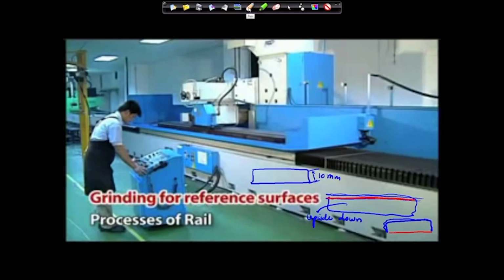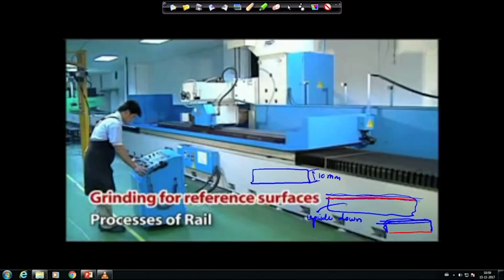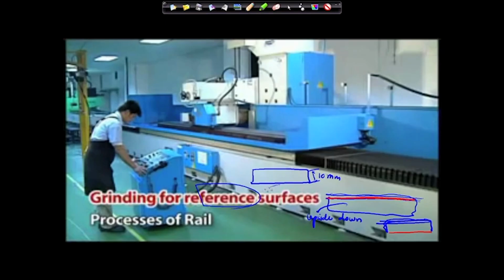Now you apply that 10 millimeters. So, you measure from here to here how much is the 10 millimeters, and again do one machining operation and one grinding operation, so that you can get the 10 millimeters. So, when your surface does not have any regular shape, at that time you have to create one reference surface, and from that reference surface you continue all the operations.